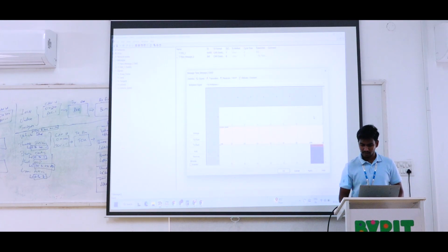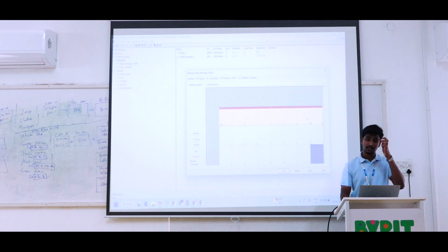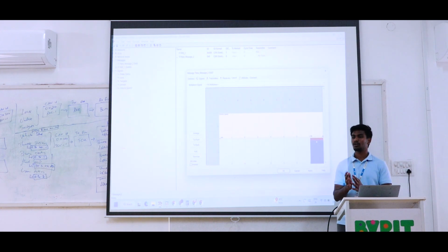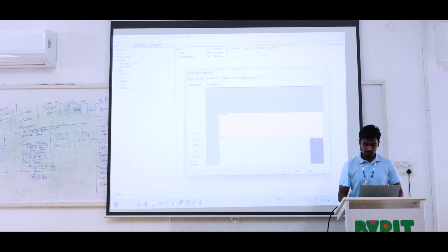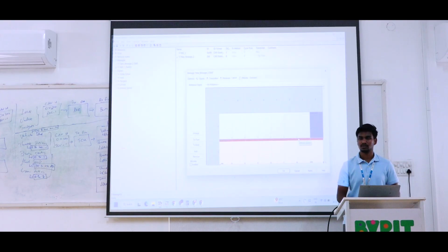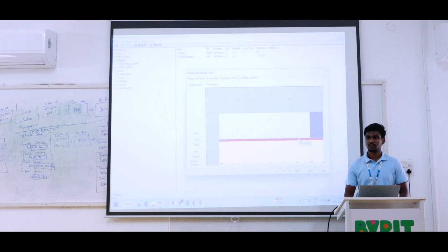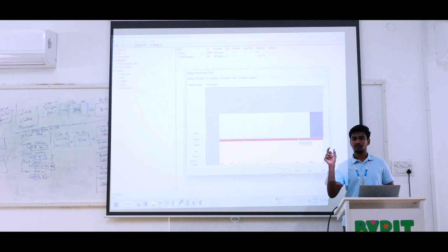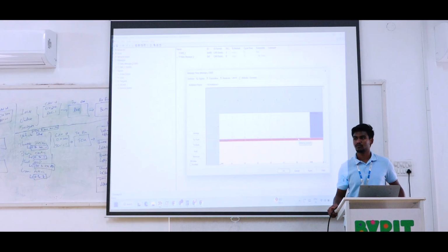Please give importance to arranging the signals in descending order. If we arrange in any order, it is not an issue, but if we arrange in descending order, we can easily occupy all the values of the bytes. For example, you created 2 more signals for the TCU also, gear position and fluid temperature. For gear position we are using only 3 bits, for fluid temperature we are using 6 bits, and for vehicle speed we are using up to 8 bits.